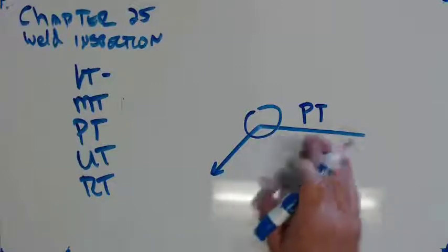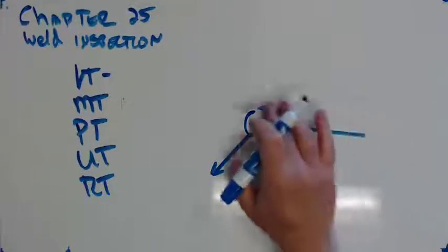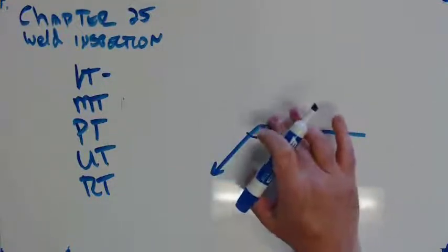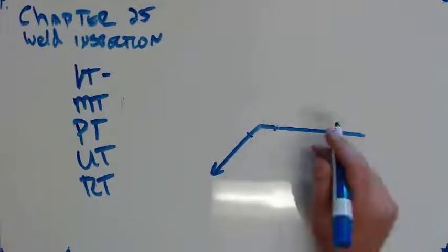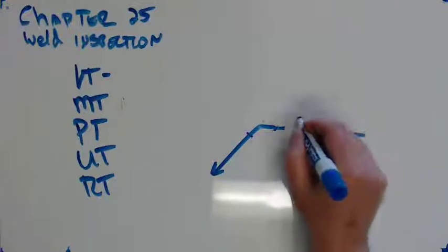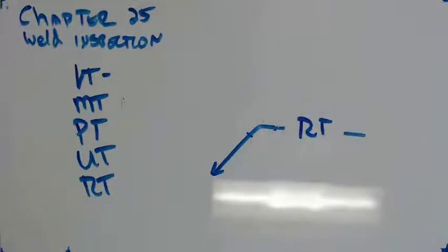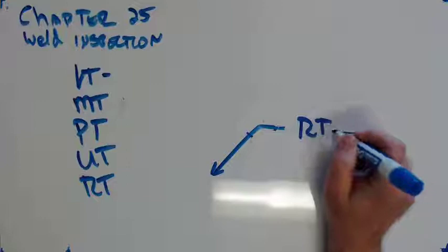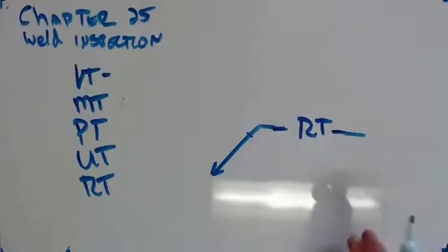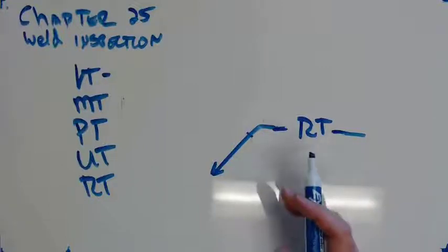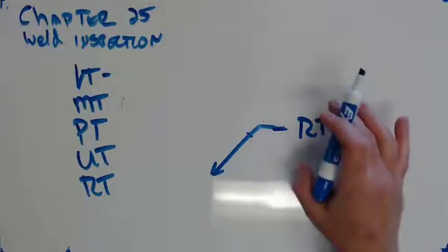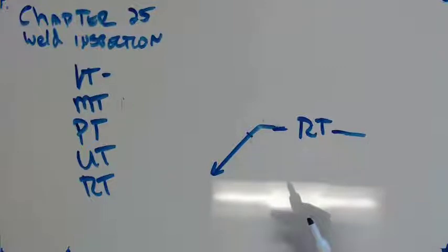Or if I'm doing a process that is going to be through the weld, like radiographic testing, you can't have arrow side or other side for radiographic testing. You're taking a picture of the whole weld. So it will actually go in the middle of the line. It's really simple. We call it just like weld symbols. Instead of calling out I want a fillet weld here or I want a groove weld here, I'm saying I want radiographic testing on this weld.